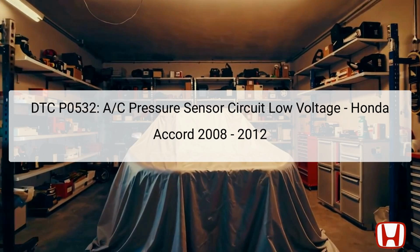The diagnostic trouble code DTC P0532 indicates a low voltage condition in the AC pressure sensor circuit for the Honda Accord models produced between 2008 and 2012. The AC pressure sensor plays an essential role in the air conditioning system by monitoring the refrigerant pressure and providing feedback to the engine control module, ECM, or powertrain control module, PCM.